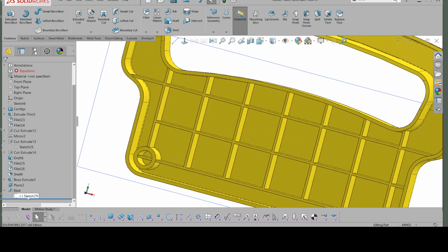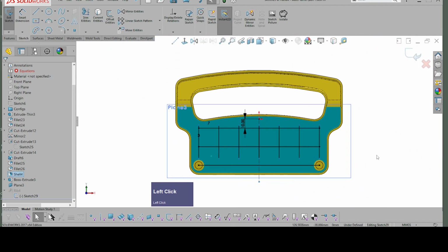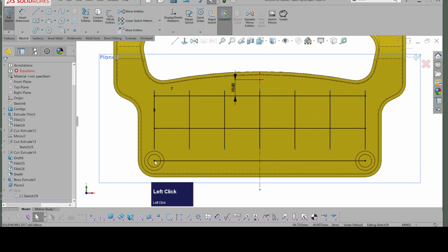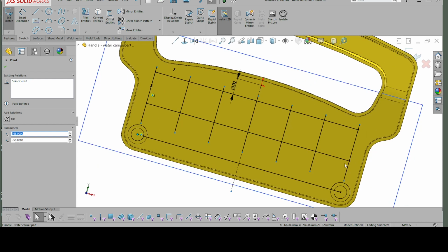All right, so we've solved that these ribs go below that point there, but we haven't solved that one. So the way to do that, go back to the sketch. I need to get that line specifically short of this item, so it doesn't go into the boss.